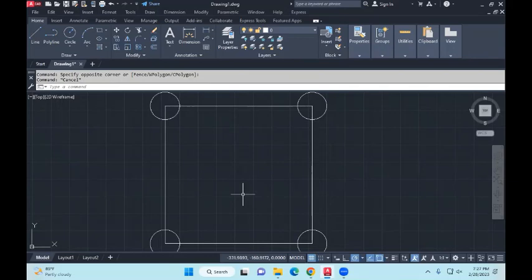Now, if you have 2 objects intersecting and you'd like to remove the intersection point, you can use the trim command. So look for trim. By the way, you'll see this note is dated 2016. These notes were produced at that time, so the AutoCAD version was 2016 and earlier, but they are still applicable today.